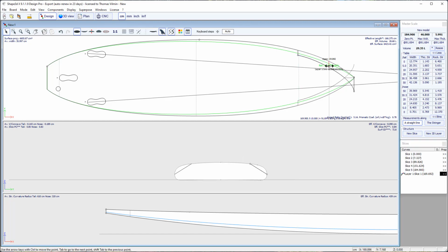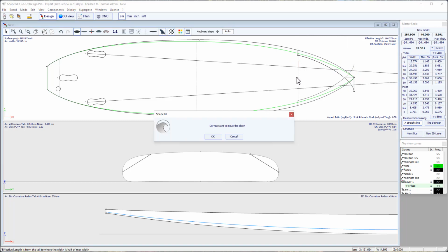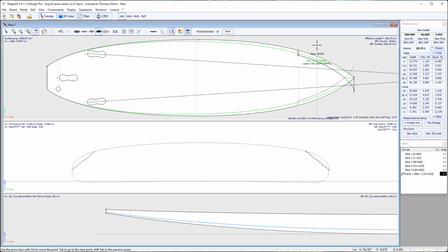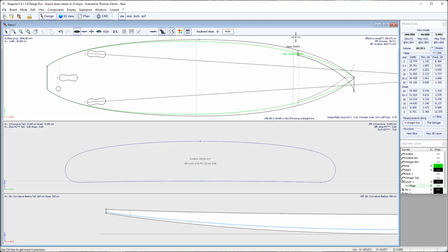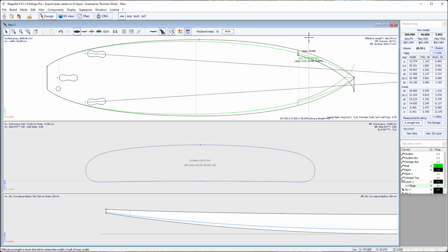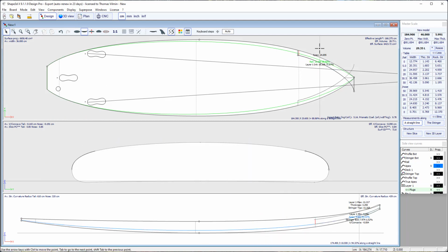And you will see that when the 3D layer crosses the center axis, it is just cut along the axis, and it can be used for designing a big nose, for example. So I put the slice here, go to slice, stick to original shape to have a continuous transition here, and